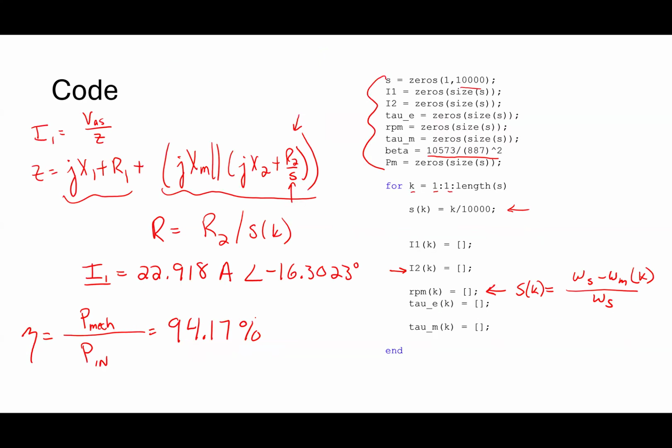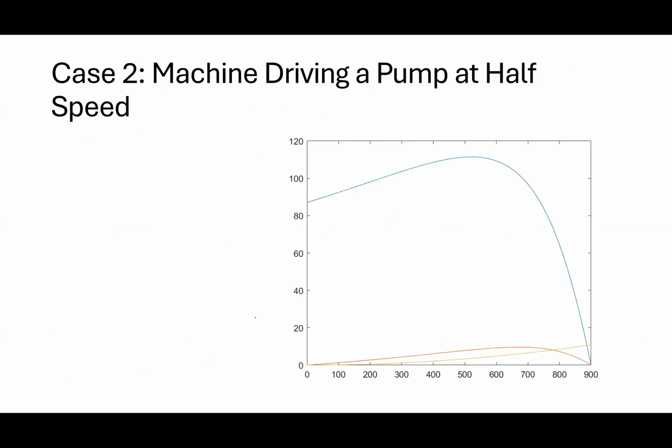All right. Okay. So now problem 3 on the homework, I basically say, well, let's hook it up to a variable frequency drive, which is what I talked about the other day. But the variable frequency drive allows me to spin it slower. So I'm running it here at half speed. Okay. So how can I tell it's half speed? Synchronous speed's gone down to 900 RPM.